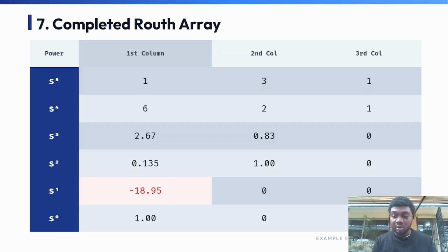The Routh-Hurwitz Criterion states that for a system to be considered stable, every single value in this column must have the same sign, that's typically all positive. We can clearly see that our sequence is interrupted by a negative value, which immediately tells us that the system's equilibrium is compromised. The table has done its job summarizing the numerical health of our fifth order system.